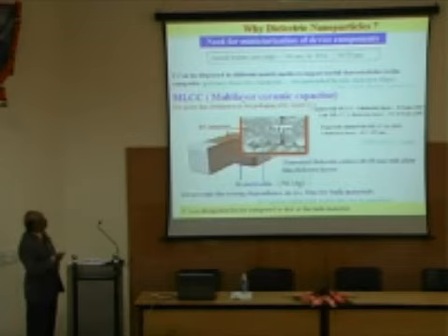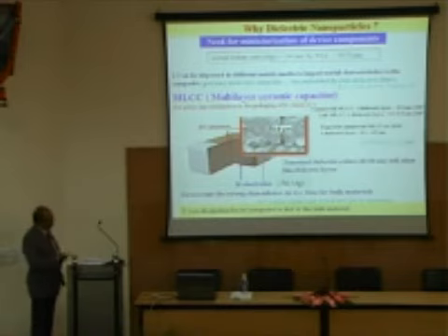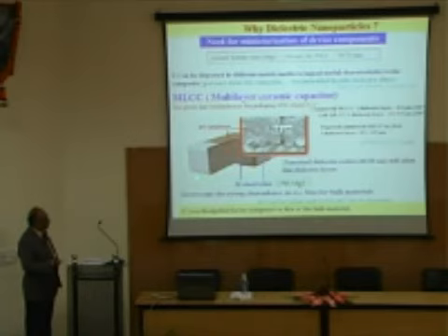Okay. I will talk a little bit about dielectric nanoparticles because a lot of engineers are here. As you know, dielectrics are very important, and barium titanate is a very important dielectric material for multi-layered ceramic capacitors. And this is a multi-layered ceramic capacitor where you have barium titanate and then metal layers embedded inside. If you take a cross section of this in a SEM, scanning electron microscope, each layer is of the order of 0.9 micron.